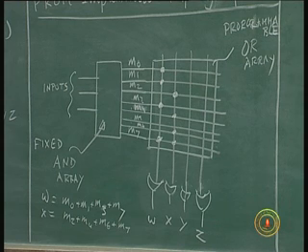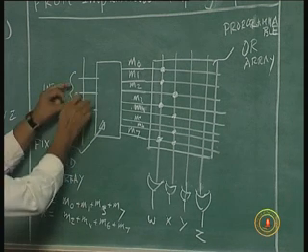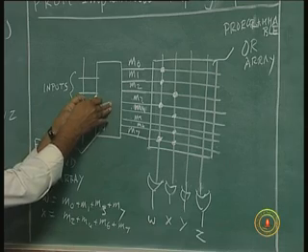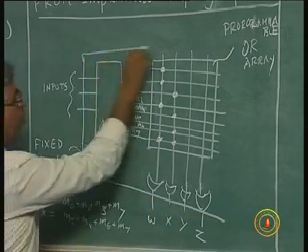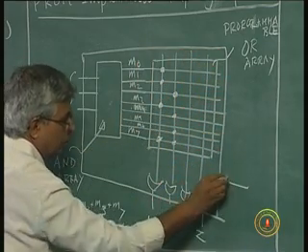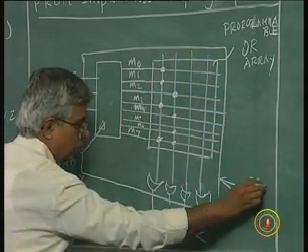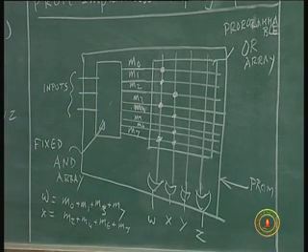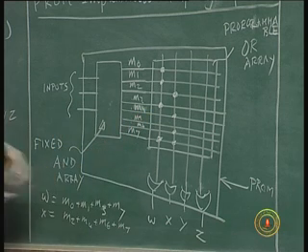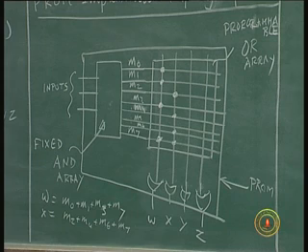Now, the programmable device comes into the picture. This is a programmable device. This total device, where these are my inputs available, I don't have any control over what is inside here. And up to this is a PROM, in which fixed AND gates produce all the minterms required, and a programmable OR array in which I can retain those minterms required for each of these outputs and not connect those inputs which are not required for that particular output.